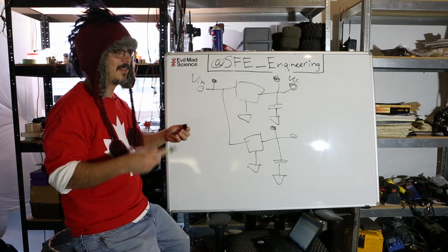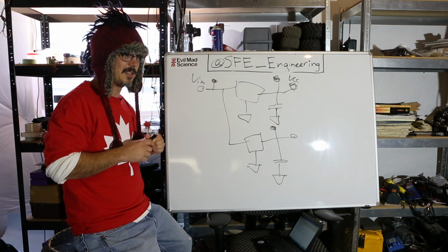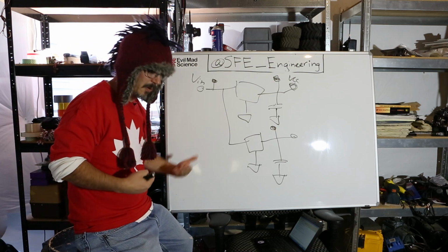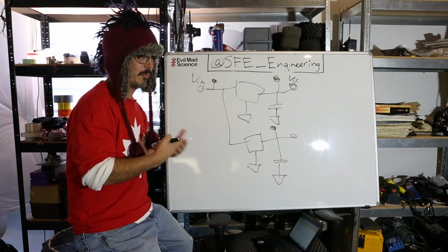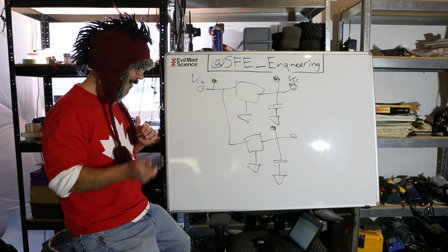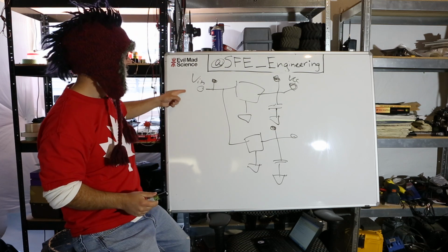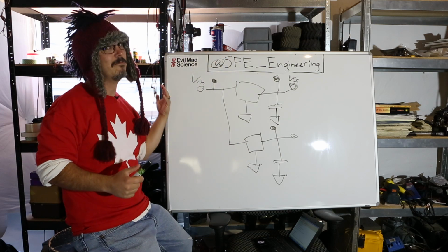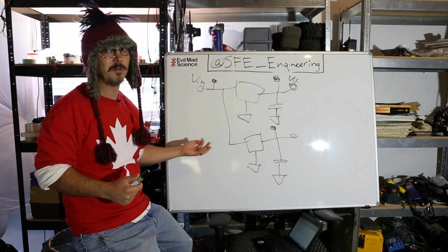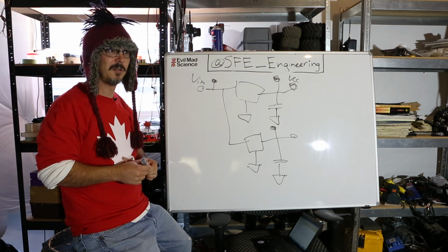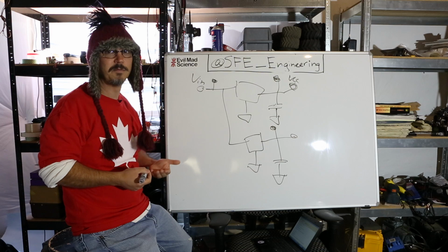So that's what I mean by, some of these things are going to become esoteric. And it's going to depend on whether or not you're testing a prototype or you're testing something in production. And the reasoning behind those test points is going to be different. In general, you're going to want to know your V in, all your regulated voltages, and the current in. That's going to give you the most information about how your circuit is doing. If it doesn't work after that, it's really dependent on what your circuit looks like and what sort of design you've tried to accomplish. That's everything.